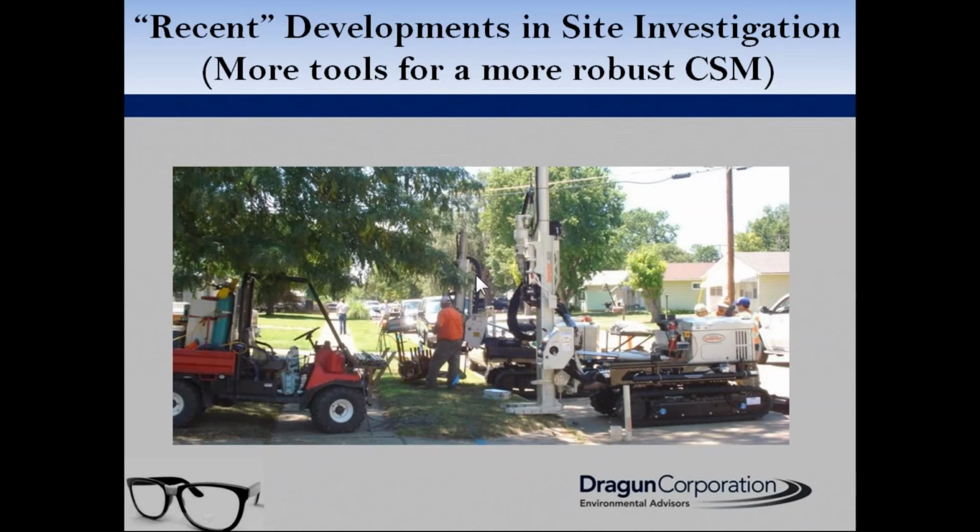So again, our GeoProbe and GeoProbe's GeoProbe are working in this residential subdivision. We're going down about 70 feet. We're using HPT to find where the permeable zones are, and SP16, which allows us to go down the GeoProbe rods and sample groundwater at distinct elevations.